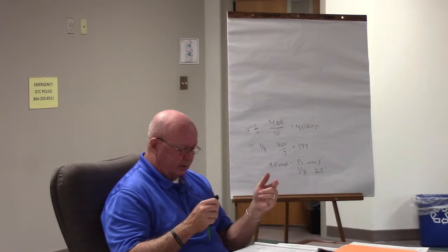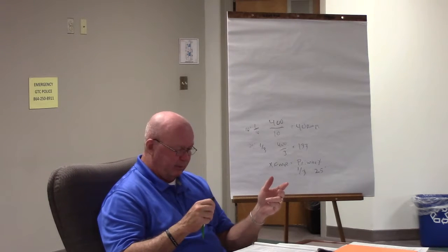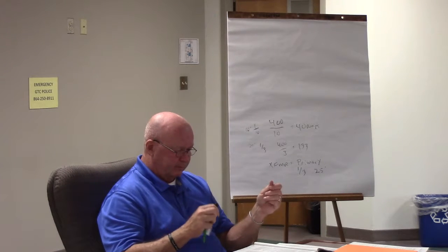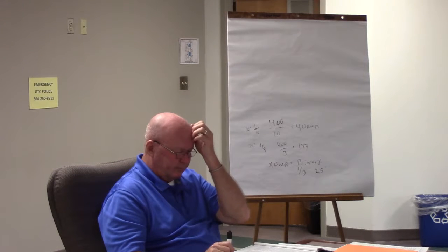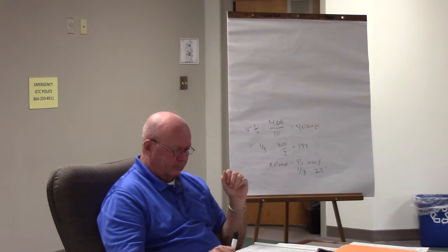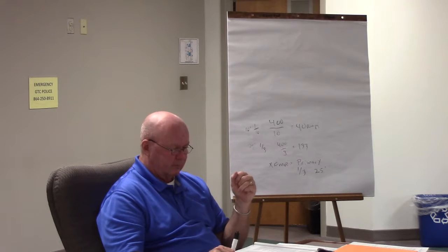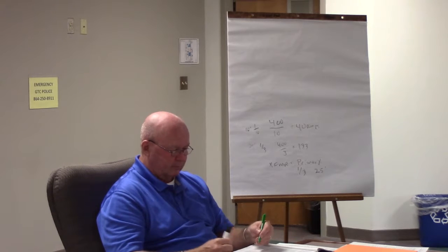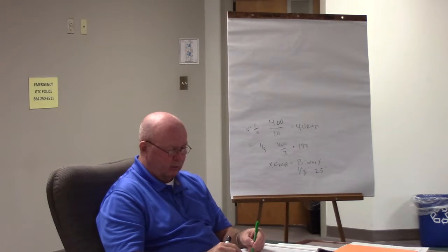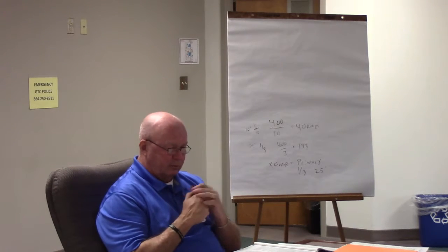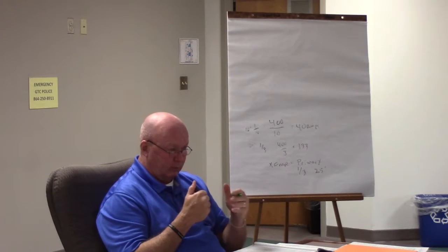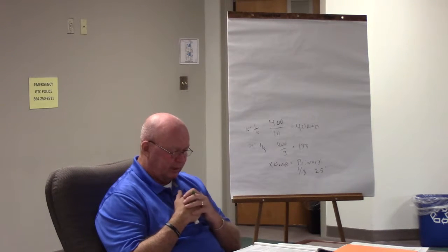Number 2 talks about secondary conductors. Read that one. The secondary conductors must have an ampacity not less than the ratio of the primary to the secondary voltage multiplied by 1/3 the rating of the overcurrent device protecting the feeder conductors. Yeah, so still 1/3, isn't it? But the rule talks about secondary conductors. We'll get into what we're doing here in just a minute and show you all what we're saying here.